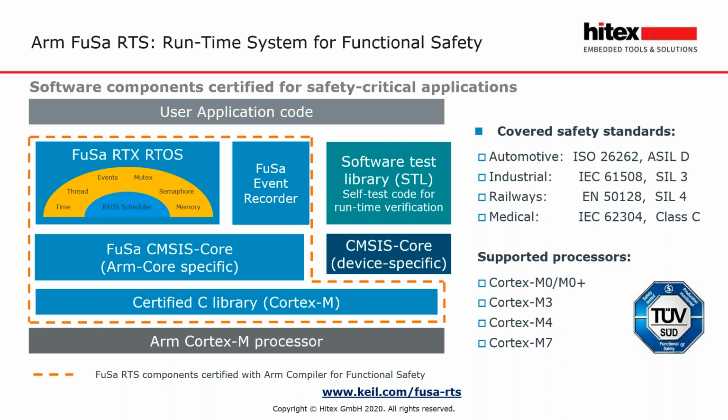There's also included in here a certified version of the Event Recorder as well. Now, this is a debug agent that sits on the chip, and it can provide instrumented messages to the development tool, but it's also very useful for getting code coverage and timing information out of the device as well.